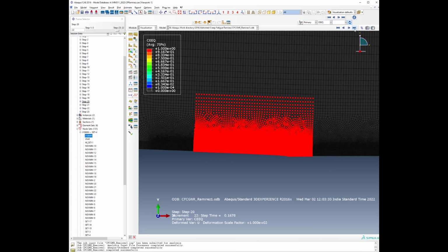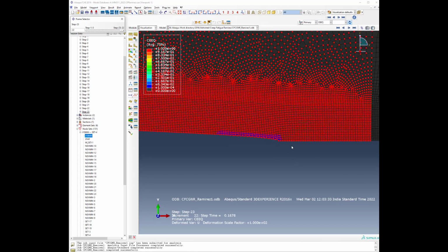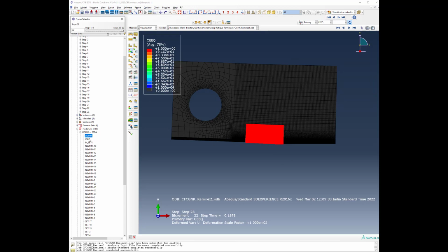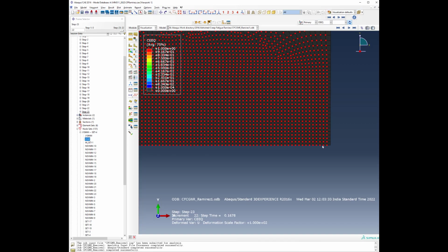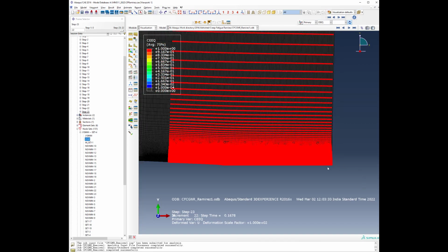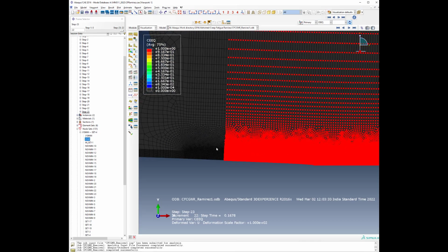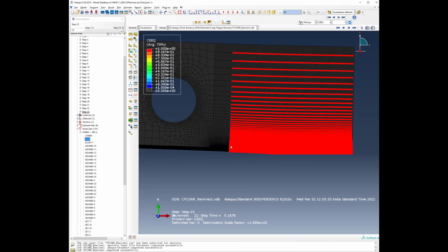So this node set, if we go to the last stage, this is our 23rd step. Our crack tip is still inside this contour. Okay, so J10 is this, and JFAR is a remote far-field contour. So this is on the boundary of the specimen. Here it's not important to cover everything because there is no deformation here. It's better to leave the hole out.